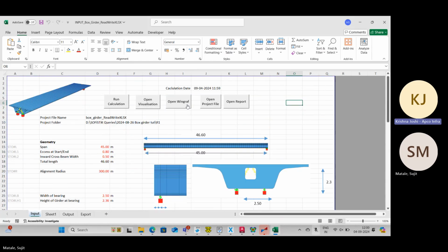Open the report from here. Just check, go to the last page, just check. It is just a 60 pages report every time getting generated with all relevant information. Sequential. See, oh, now it was 4 MPa tension. Now it is reduced to 2 MPa. Further, I need to increase 2 more strands. I do that and I reduce it, take compression 1. At least your design will be done. Drawings to check over, if you want.